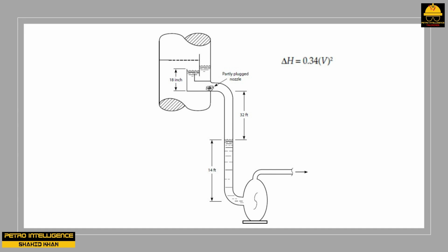The 0.34 coefficient shown is the conversion of potential energy to acceleration, which includes a reasonable allowance for turbulence and friction. The theoretical coefficient is about 0.18, which only includes acceleration. In my designs, I use 0.34 for nozzle exit losses, which my experience has shown represents what I actually observe in the field, plus a small safety factor.